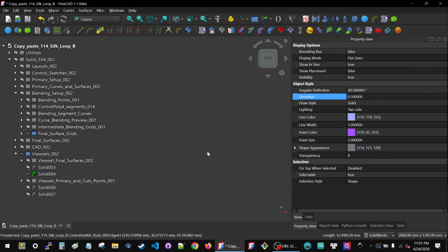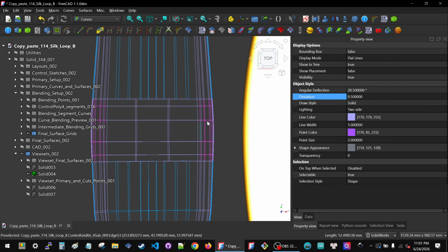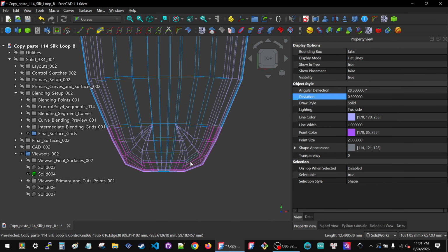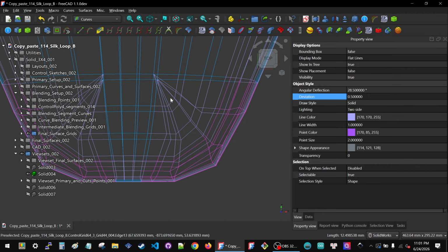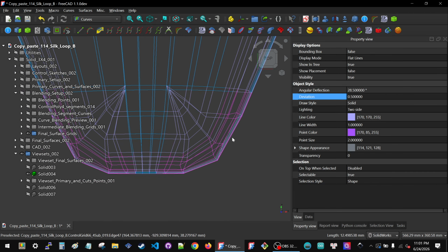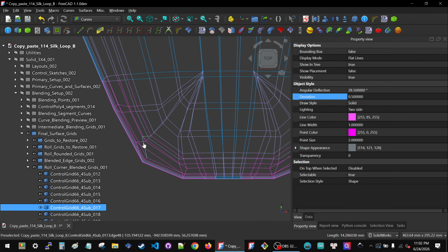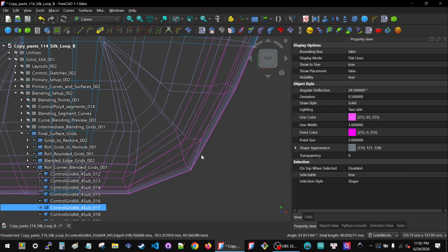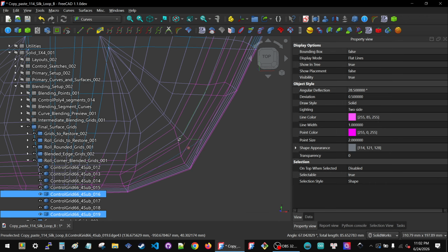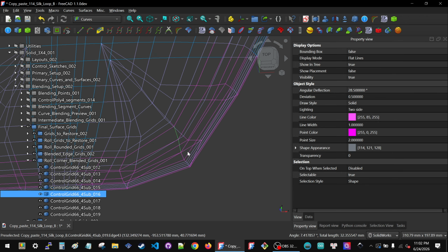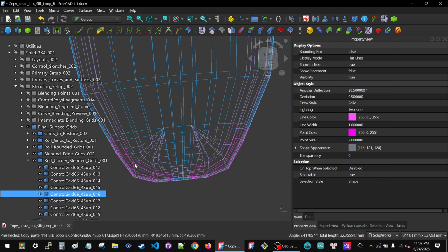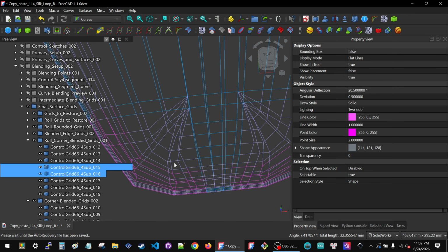And even though the default values of the double blend are pretty reasonable in cases where you have 4 corners or when everything is at 90 degrees, the default values are pretty bad when you have one of these rounded triangles. So they're bad in the sense that they have this kink between these 2 lines. But by going to each subgrid, you can carefully adjust those and align them a little bit better, like I did here. See? These 2 lines right here were the equivalent of these 2 lines over here.